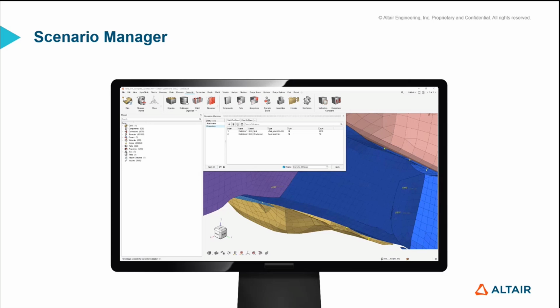With the improvements that came in 2022.1 with the metadata mapping from the parts and from the CAD assembly, it means that effectively, if your incoming CAD represents your connectors and that contains metadata on the part level, we can map that part level to the connector. We can independently have controls on how the customers want to model their connectors, and then using Scenario Manager, we can robustly apply those controls to those connectors via that metadata that comes from the part.